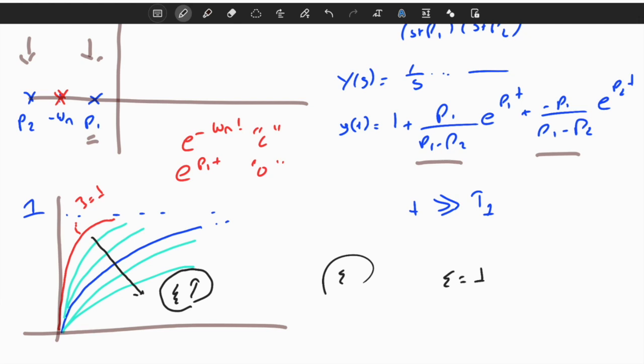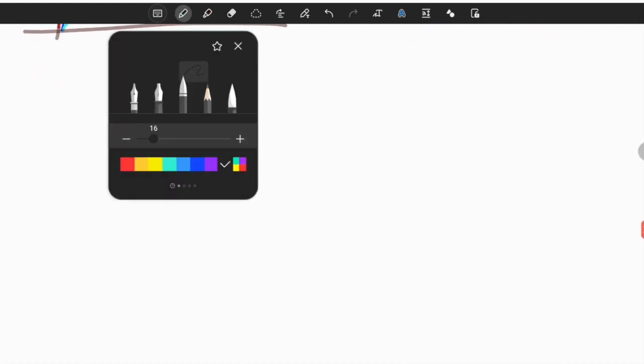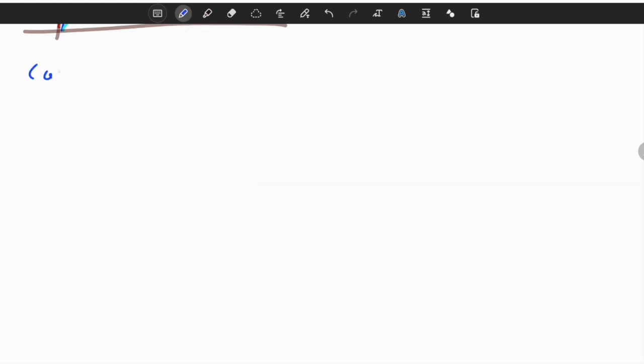Okay, good. That's nice. Now we will move on to the third case. Case 3, where psi is less than 1 and larger than 0, which is called an underdamped system. Why must this be underdamped? Let's just look at the angle. Underdamped means that the damping, the level of friction, resistance or dissipation, is not enough compared to the critically damped case. We will see what it means in a second.